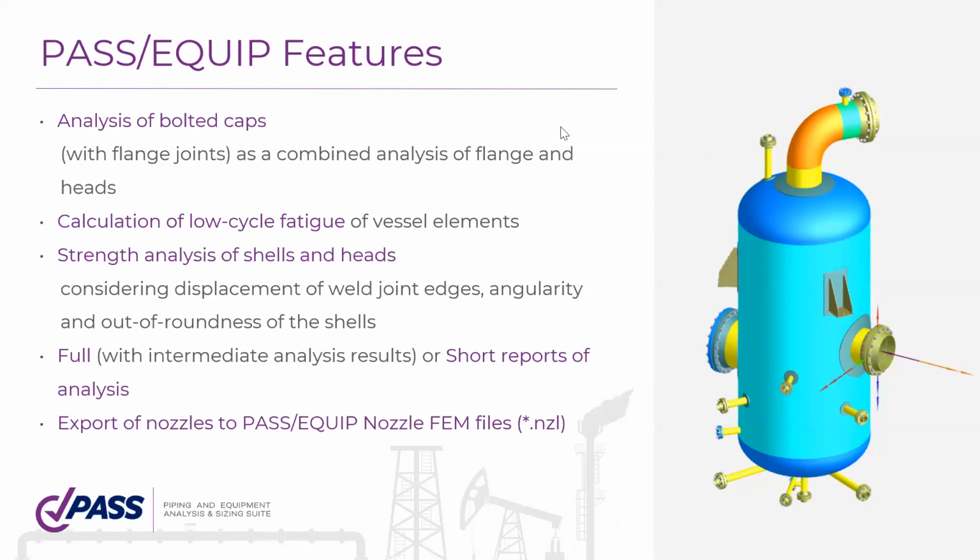Some other features, we have very detailed analysis of flanges, bolts, and some other connections. And we can also make fatigue analysis of vessel elements. And of course, we can do some additional analysis of shells and heads with some defects like out-of-roundness and so on.